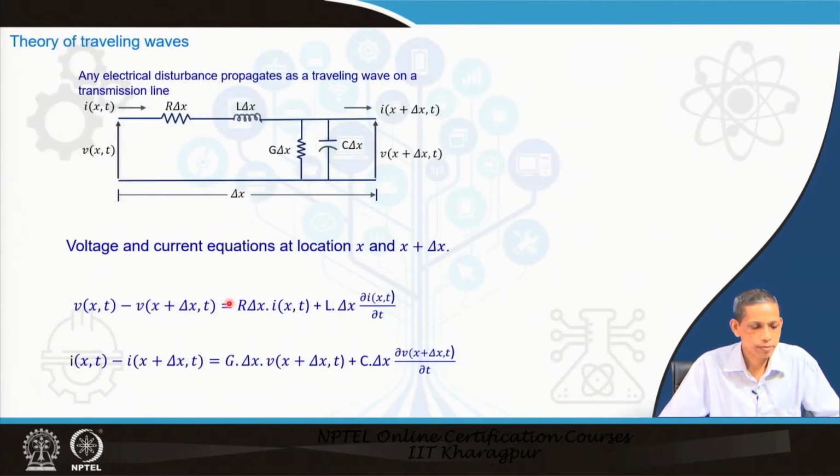Let us go to what the travelling wave associated with a fault is. Any electrical disturbance like lightning, load change, switching, or a fault originates a travelling wave because of the sudden change in voltage and associated current. This step change in current and the related voltage leads to waves being generated, which propagate both ways in the system.